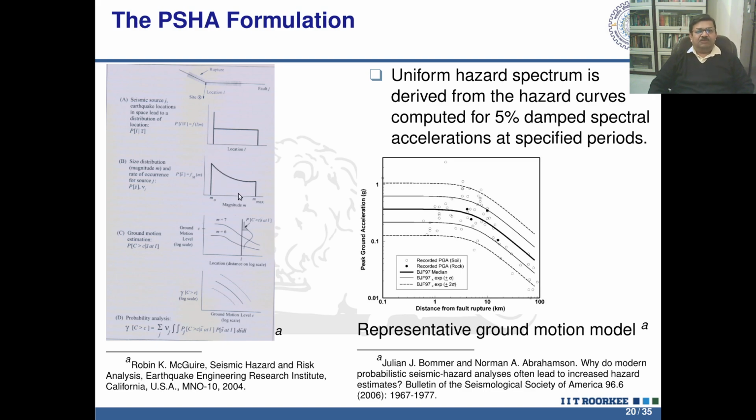And then from these, the magnitude and distance, where for the site, how far it is from the location, so what is the distance measure. Because earthquake is an unknown quantity, we generally assume earthquake can occur anywhere. So distance probability is uniform over a certain range. The magnitude distribution depends on the seismicity catalog, past seismicity occurrence data.